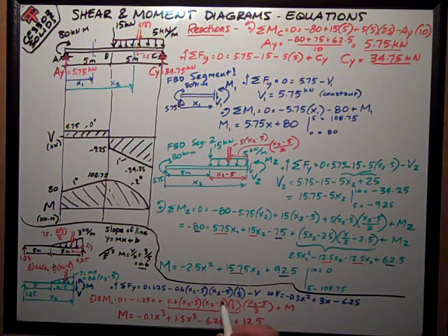So I've already got a quadratic equation. Now I'm just in the shear. I do all the math, express it out. V is equal to negative 0.3x squared plus 3x minus 6.25. And I would have to evaluate that if I was graphing this at 5 and 10. It's going to be a curve, a second order curve for a shear diagram.